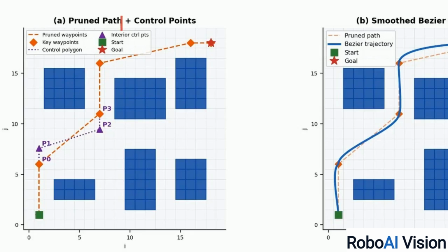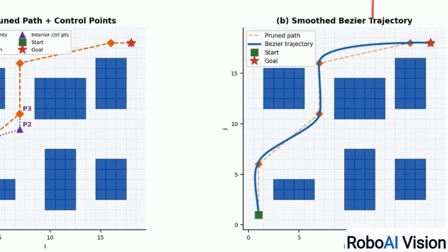The pipeline takes the sharp, linear waypoints on the left and passes them through a B-spline generator, producing the rounded, continuous trajectory on the right. The discrete waypoints act as control points to shape a continuous polynomial curve. This enforces C2 continuity, meaning curvature changes smoothly without jumps.